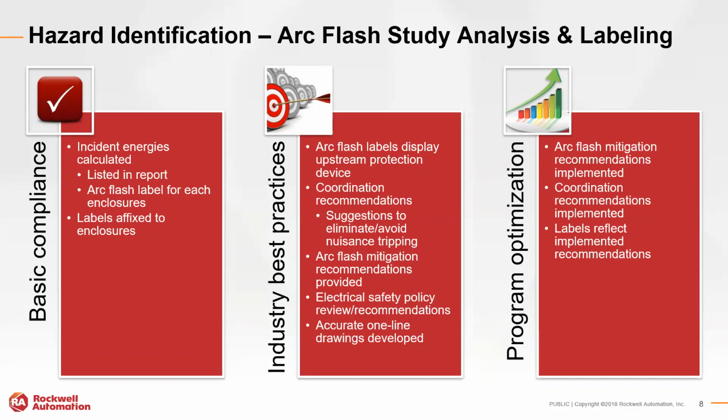So like I mentioned, simple recommendations like changing those breaker settings could be applied by your own internal personnel in many cases, quickly and at no cost, sometimes without requiring de-energization, depending on the breaker that you have installed. Sometimes you can do that very easily and quickly during a scheduled shutdown.